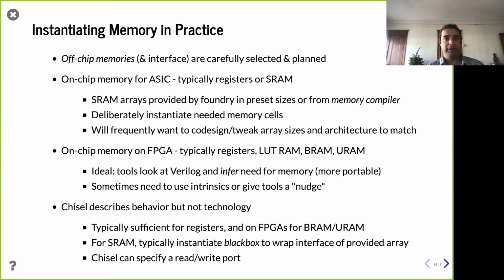So for ASIC, you're definitely spending a lot of time on this. For FPGA, fortunately, it's a little simpler, right? There are, of course, registers in FPGA. There's something called LUTRAM, BRAM, and sometimes URAM on Xilinx. In other words, you have your normal flip-flop registers, there's some sort of block RAM or BRAM, and then there may or may not be other exotic things that are vendor-specific.